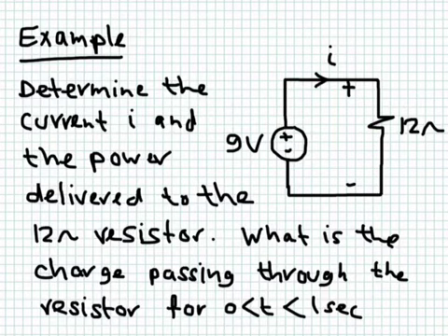This is a very simple circuit. One voltage source, one resistor. No one said anything about it being a non-linear resistor, so we have to assume it's linear. Then the current is equal to V divided by R. So I is equal to V divided by R. You are able to get the value of I. If you know I, then you know the power.